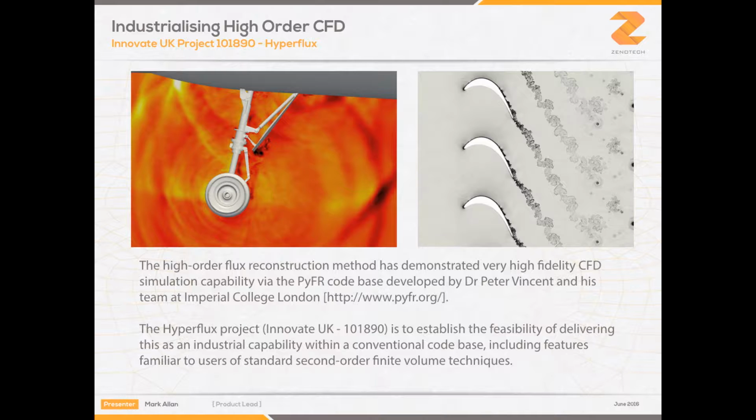So the high order flux reconstruction method has been demonstrated to be very good at simulating these types of flows, and the PyFR code, which was developed by Dr. Peter Vincent and his team at Imperial College, has been used for these simulations. So the Hyperflux Project was set up to try to bring this state-of-the-art technology to industry, and it has been done through the implementation of this method within a commercial software code, which was ZCFD in this case. We've tried to focus on making the use of the method as simple as possible for those who are more familiar with standard second-order finite volume techniques.